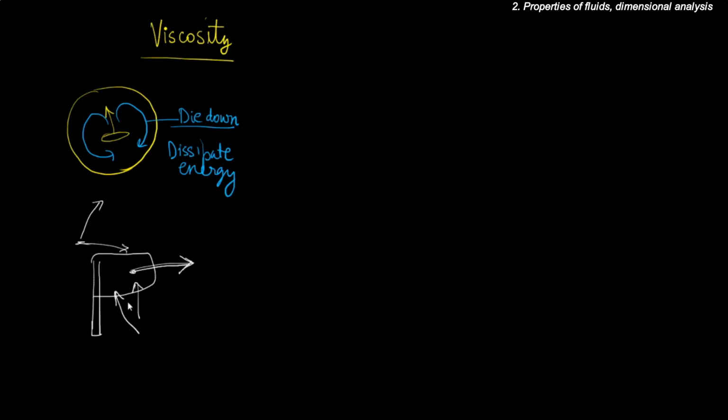However, if the viscosity is higher, a larger amount of fluid would be immediately displaced because of the motion of the fan, but at the same time it would make us tired because it would require a larger energy to make the motion of the fan. Let us consider what happens when a fluid element is deformed because of the action of a shear. Now the top surface has a net higher velocity as compared to the lower surface.